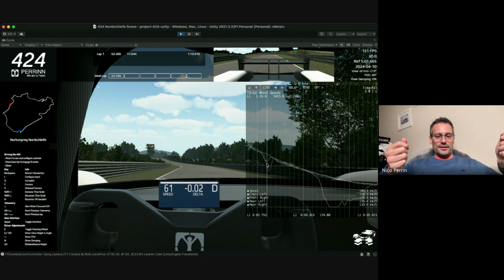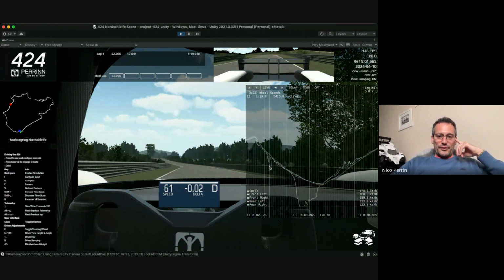And the way you feel it in the car is the car suddenly steps. And if it gets worse, it would spin. Obviously, for the car to spin, the rears would have to slide a lot more. The reason they don't lock and stay locked is because it's a bump. The car has basically gone in the air and come back. So that's very typical of high-speed hard braking.